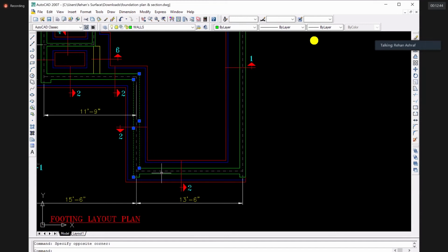So what you are going to do is simply copy your ground floor plan, and while copying the ground floor walls, you should turn off the windows layer and doors layer. It means when you copy the whole plan, windows and doors would not be copied when they are turned off. Simply copy the walls to the side. Then next is to make the walls continuous, meaning that under doors and under windows there would be wall continuation, right?